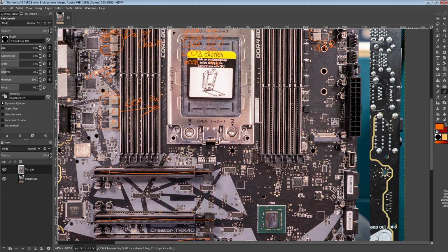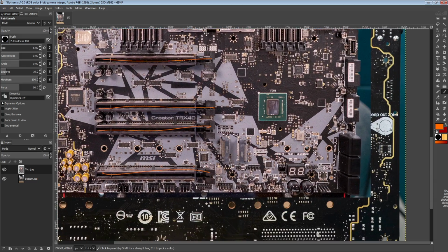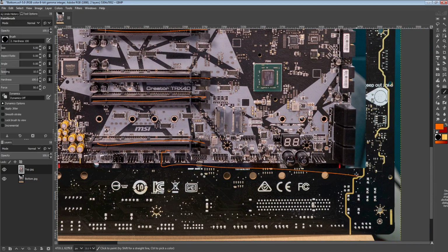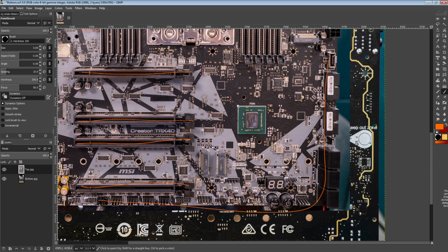And it's just like, well, is the 24-pin going to be okay with that? Not really, because MSI's on the folded metal pins, so their 24-pin is even weaker in terms of current handling capability than some of the other motherboards out there. This really should have had a 6-pin power connector somewhere along the bottom edge. Or really, anywhere in this area.